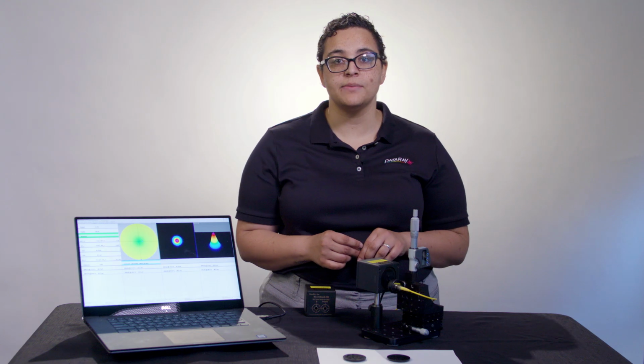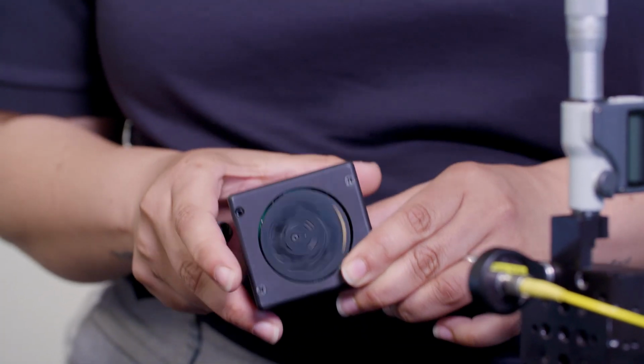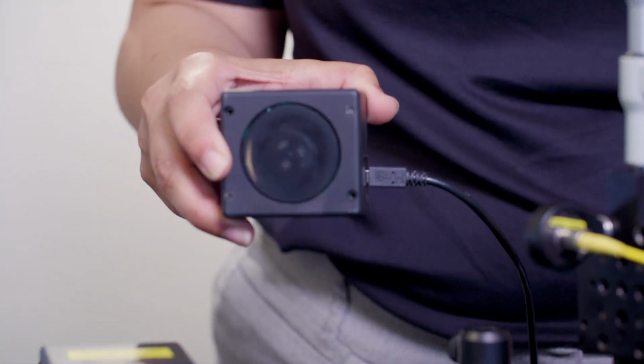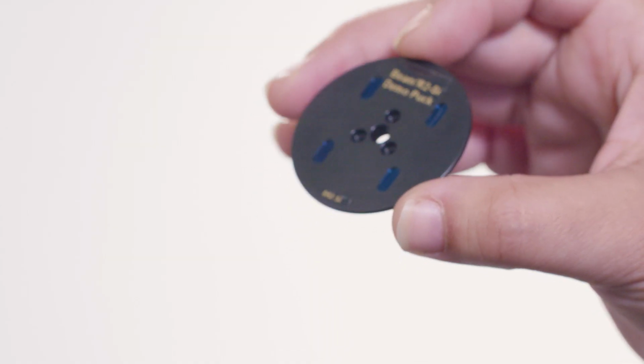The BeamMap2 comes in both single detector and dual detector models. The different detectors enable use at 2 different wavelengths. While both detectors cannot be used simultaneously, it is very quick and simple to switch between them, and with the alignment assistance and quick focus capabilities, switching takes just a moment.